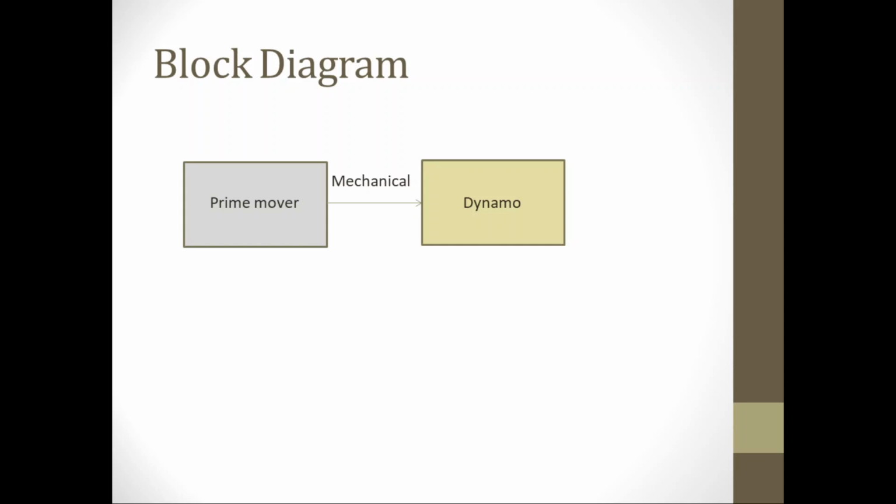Once the mechanical energy is present, when the DC generator is added with an excitation, or basically added with magnetism, the generator will be able to build up voltage, and in turn will have an output of electrical energy.